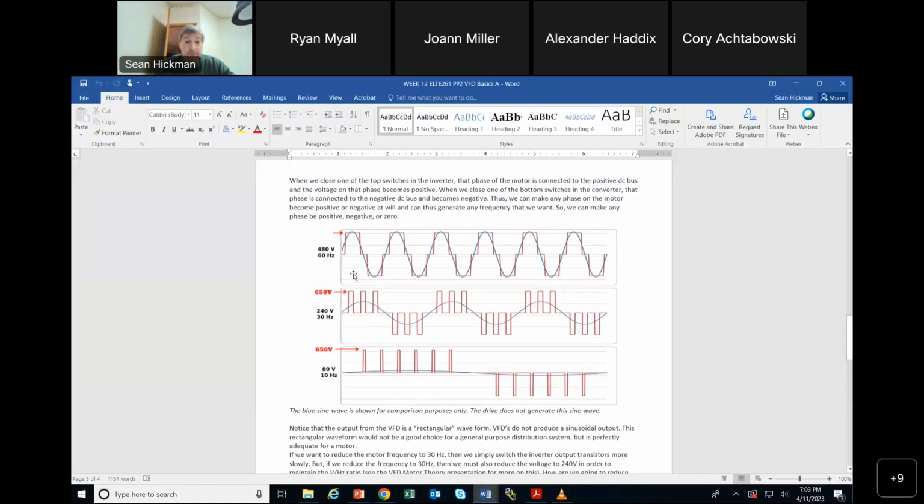And so once again, if you keep this on longer here and you pulse it longer here, whatever switches you go, faster, longer, you can get 480 volt 60 hertz, because you're pulsing the 650 volts. And once again, you're talking about RMS. Because you're not using the outsides of this, you're looking at about 480 RMS.